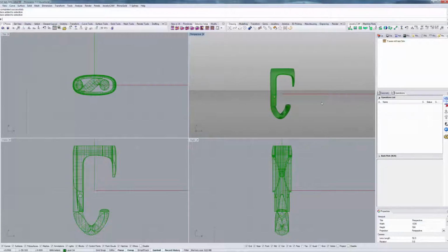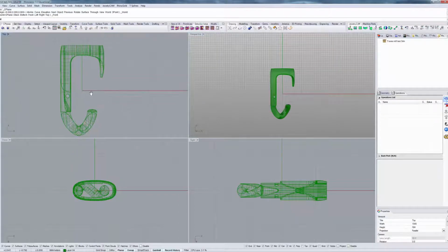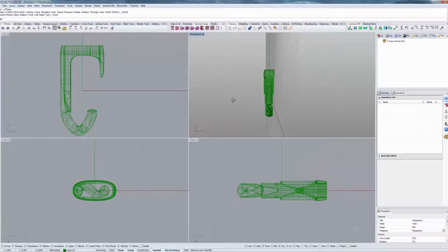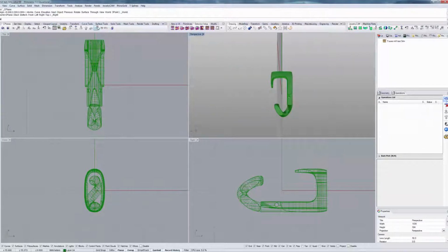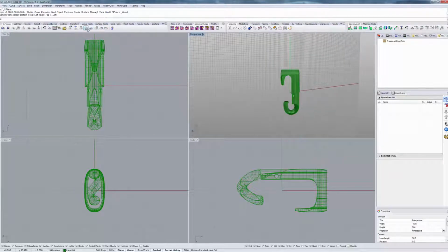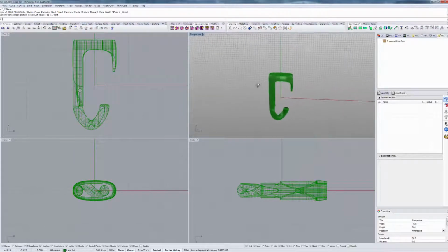perspective, your construction plane, for example, this way, so you can see this reflected in the top window. You would then draw boundary curves around either the whole model or parts of it. You'd mill it out. Then you would position the model this way. Then you'd mill parts that are exposed this way. Flip it over again, and then again. So this way you would cover all 4 sides, and your model would be cut out, at least on the outside, at that point.